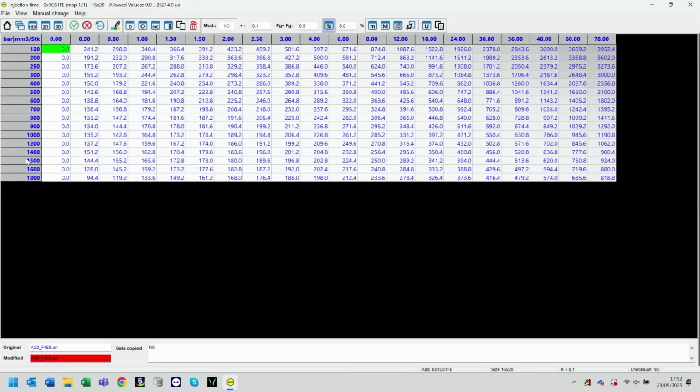You'll also see on the left-hand side, I've got no fixed point to start from. I've got no RPM to reference against. I'll look at my fueling across the top, and I can make some changes in this bottom left-hand corner, maybe to the 36 on the fuel, maybe 48, similar to our SOI injection time map. But I haven't got a fixed point for the rail pressure. I don't know what rail pressure to start at.